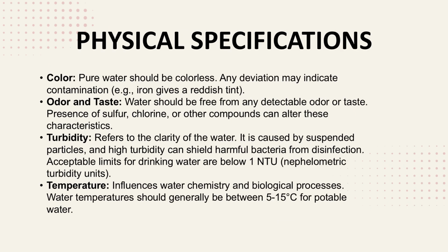Let's take a closer look at the physical specifications of water, which are especially important when considering water for drinking or domestic use. Color. Pure water should be colorless. Any change in color may signal contamination, such as a reddish tint indicating the presence of iron. Odor and taste. Water should be free of detectable odors or tastes. The presence of compounds like sulfur or chlorine can alter its smell or flavor, which should be addressed during treatment.